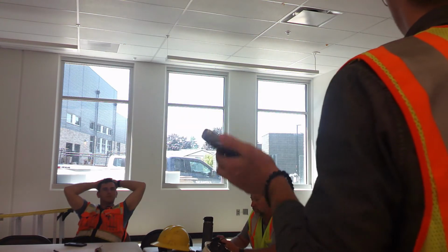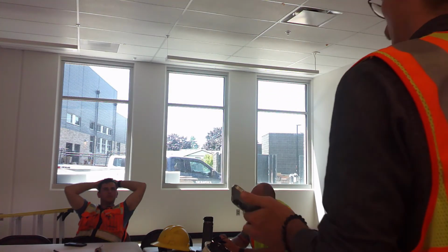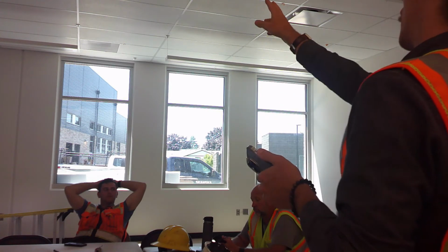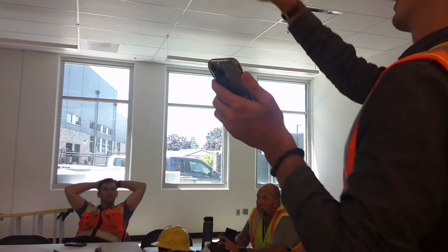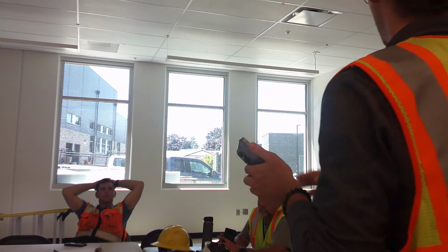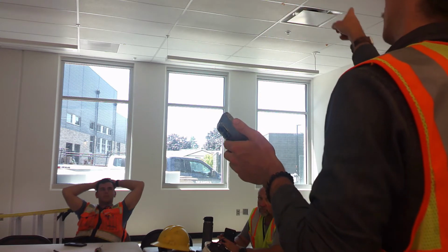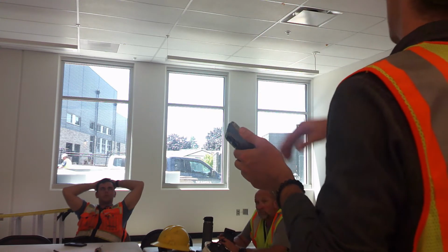All the classrooms are just using the 2 zones. You got daylight zone 1, daylight zone 2. So zone 1 is going to be talking to group 1 and group 4. Zone 2 is going to be talking to group 2 and group 5. So these 2 lights are going to dim the same based on the photocell, and those front 2 are going to dim the same based on the photocell.